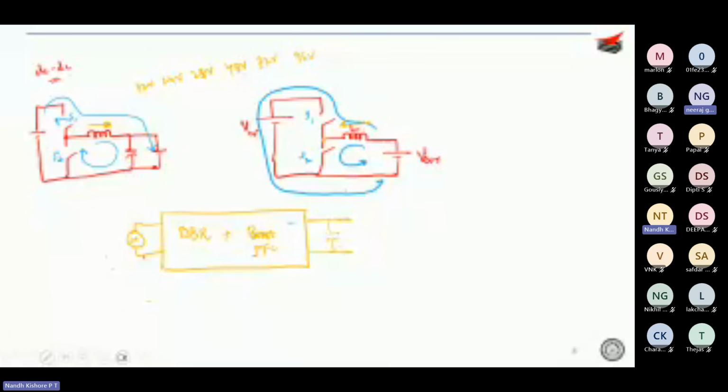Yeah, here the voltage would be 400 volts, more than supply voltage. So this is your VN. Peak voltage can go till 230 root 2 V peak. So that has been boosted up to 400 volts, but what I wanted is let's say 48 volts.